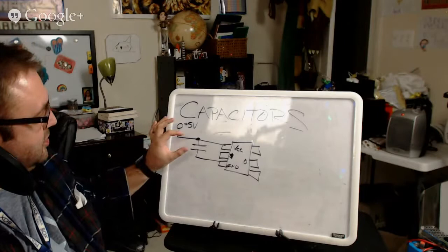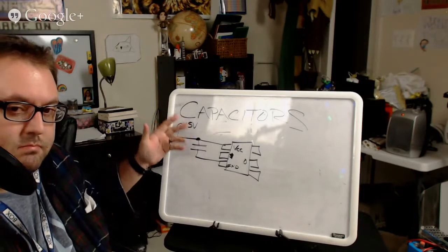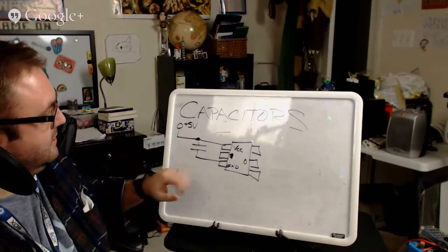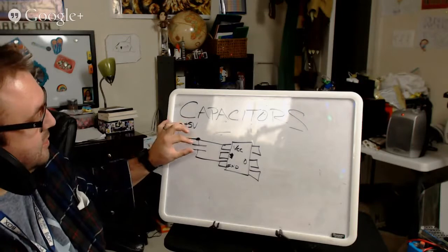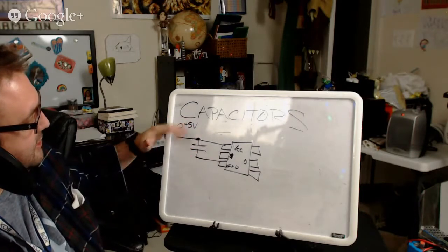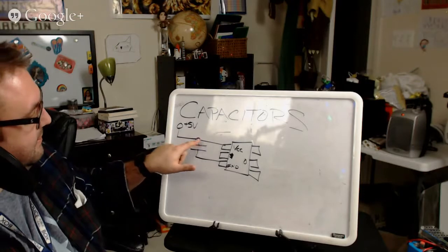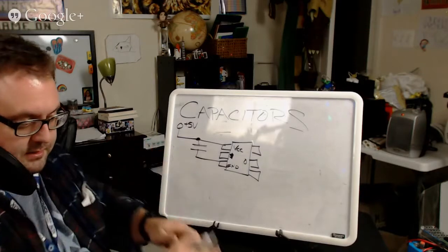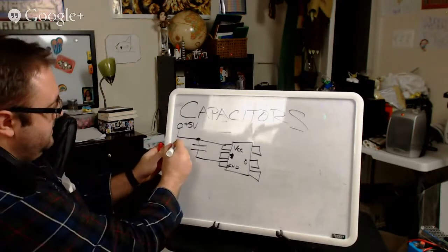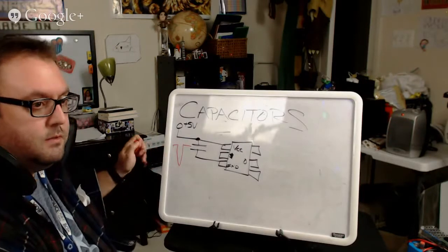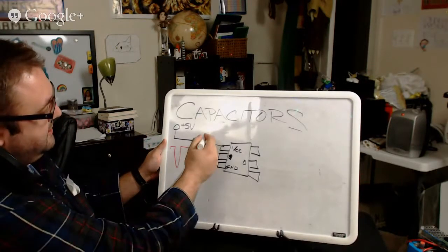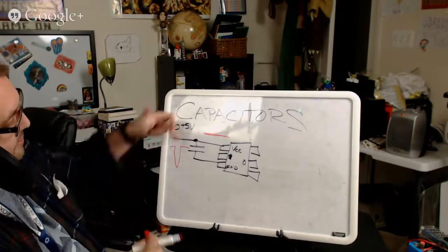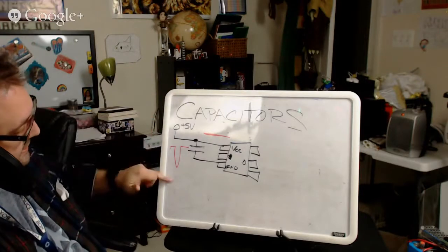What they do is they charge up. They're usually small, a microfarad, maybe a little less, a little more, depending on the surrounding circuits. It stores just enough charge that if there is a drop on the line, a real quick little spike, instead of having that spike come into your chip, your capacitor just filters it out. So the chip, after this point, still sees a constant voltage and doesn't see that drop.